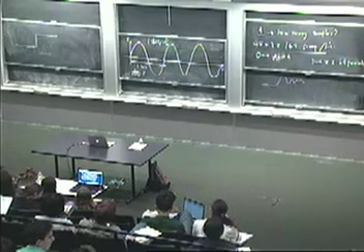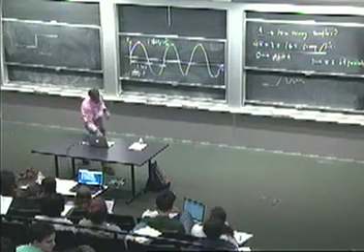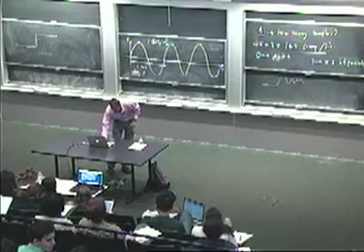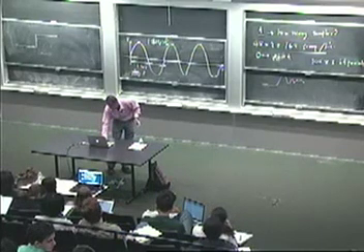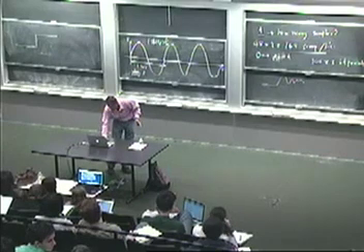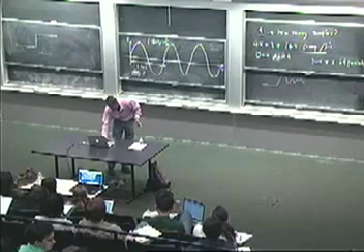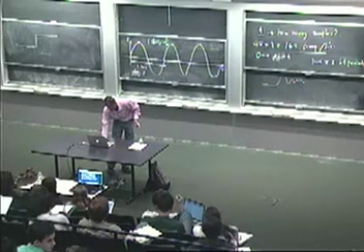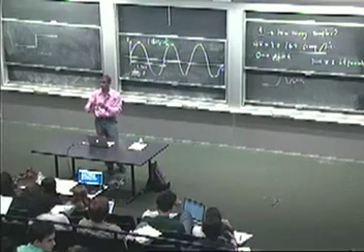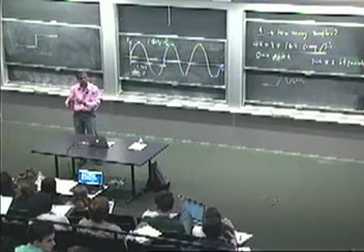You're very likely to be able to decode, because essentially the receiver can decide that when ones happen, it corresponds to something over here at 0.35 or 0.4 volts. When a 0 happens, it may correspond to something like a 0.1 volt here, which means I can pick the middle point and slice it at that middle point to determine whether the received bits were a 0 or a 1.